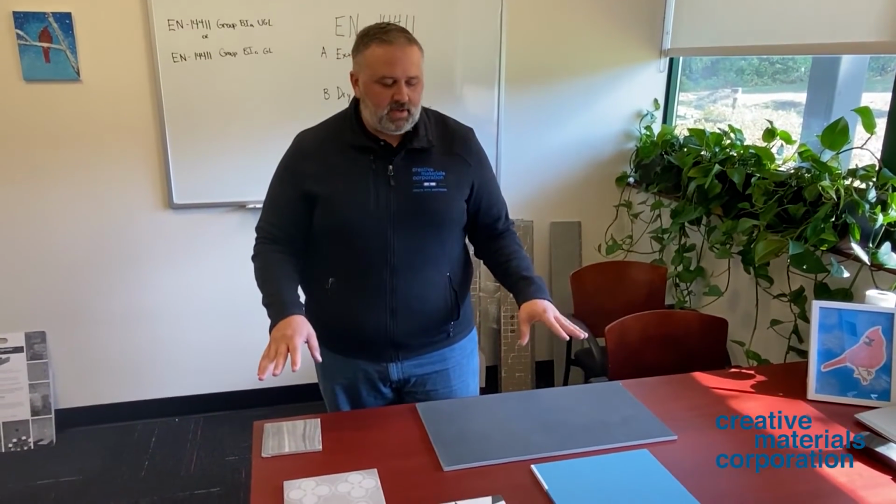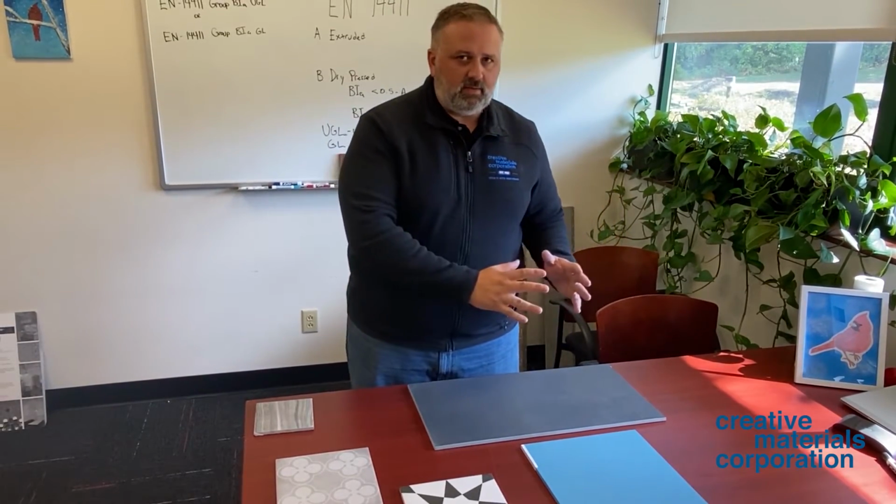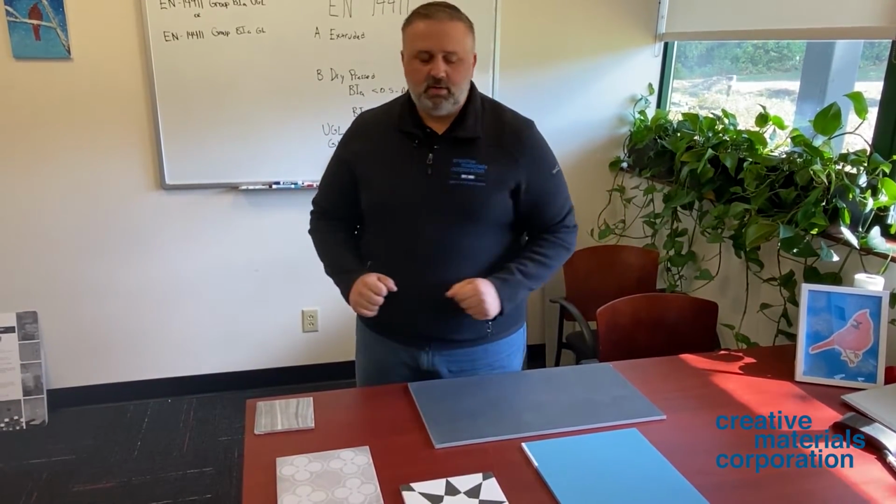So here on my desk right now, I have various tiles, all of which are porcelain tile. They're all made with the body being raw materials like quartz, feldspar, kaolinite, the typical products that are used to produce tile, but the surface treatments are different on each of these, and I'll explain why in a second. Again, we're used to thinking about through body and glazed, color body, glazed, non-color body. What we really need to think about is glazed, unglazed, okay?